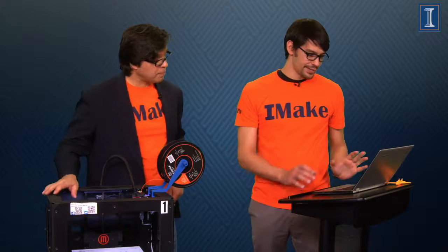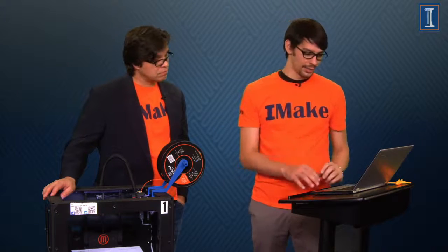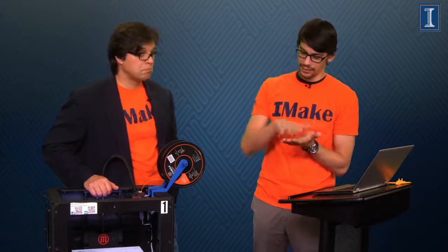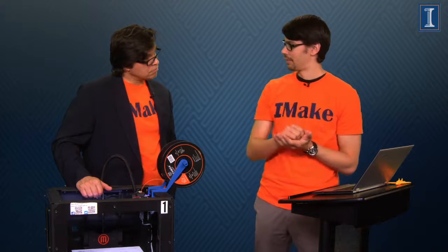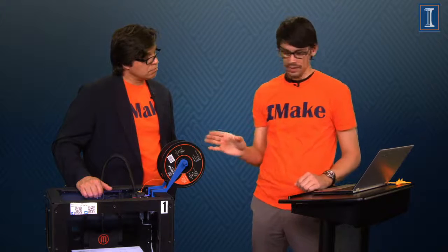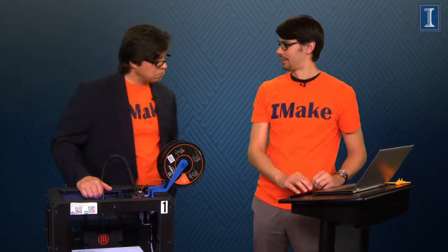That's right. So slicing is the essential step between your 3D part file and a 3D printed file. What slicing software does is it takes the part file you have and cuts it into a large number of layers. You can imagine taking a slice with a chef's knife of your 3D part. And on each of those layers, it will trace the path that this end effector takes to draw the part on each layer. By successfully drawing each layer, eventually the printer will print the part. So this is basically making the recipe or cookbook for this particular print file. Okay, that's a great description.